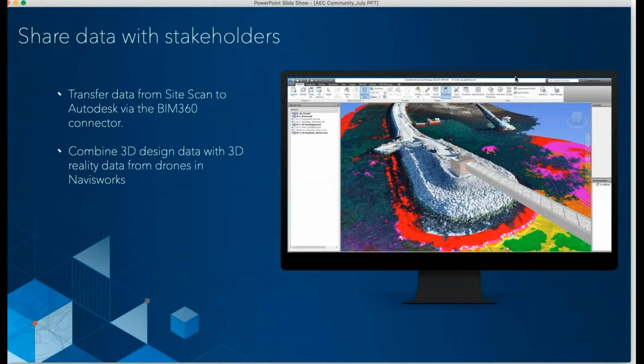A key component to this is being able to collect ground control points so that the resulting drone data is in the exact same coordinate system and has the accuracy required in order to do this. And what they've done is actually taken chevrons or X's that are kind of spray painted across the project. And in some cases, SiteScan can automatically detect those and auto tag the ground control points so that the resulting data products are accurate without a whole lot of manual intervention.